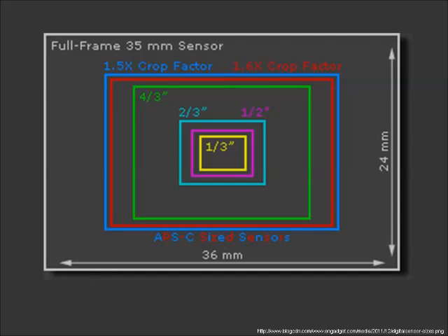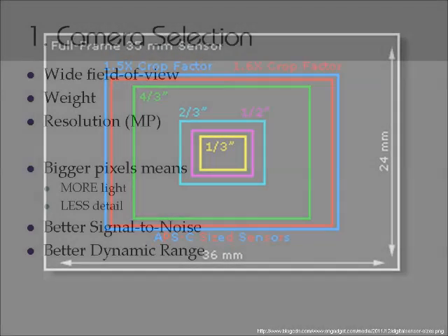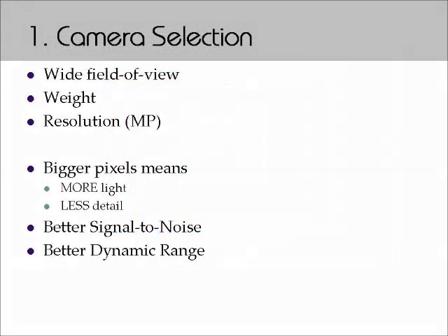Now as soon as you change the focal length and the size of the sensor, the effective focal length, or the field of view of the camera, changes. And you need to be aware of that when you're doing your mission planning, because it will vary for each and every camera you have. Effective focal length is used because pre-digital with film cameras, they were 35mm, so all lens at focal lengths people were familiar with were related to 35mm cameras.